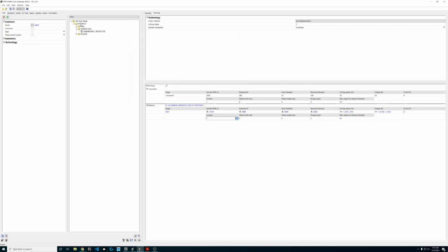Just make sure that all your stuff is jiving. Make sure that through coolant in one post is coolant 1, and through coolant on one of your other machines' post is coolant 3. That's bad juju because that might be defined as air for that tool.